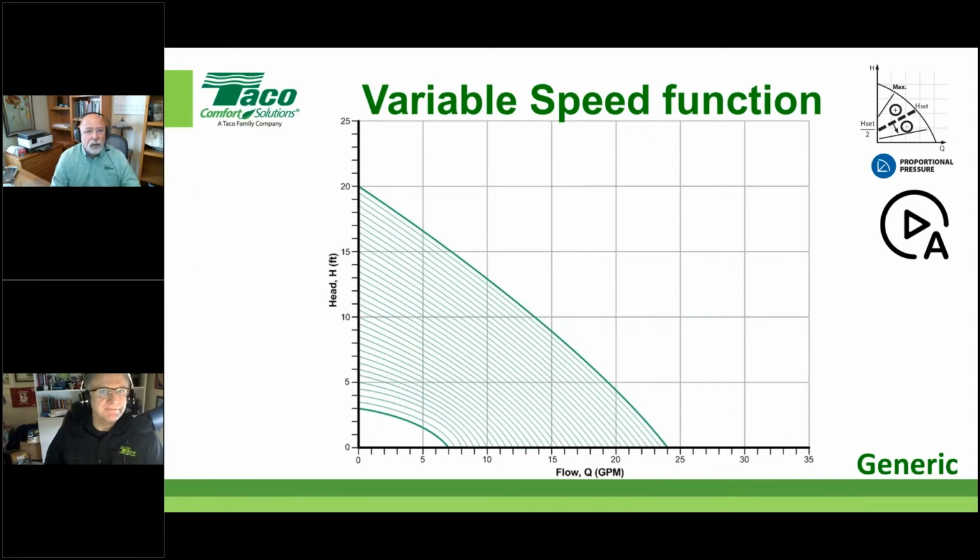Asked Kevin Walbridge. Well, it's looking at the data that the motor is feeling, right? So the onboard computer in the little drive that's on the ECM is looking at things like RPM. It's looking at amp draw. It's looking at wattage consumption, and out of that information, it sees a change based on hydraulic changes within the system, and it makes a decision whether to speed up or slow down based on the setting that you've put the pump in. And hopefully that answers that question.